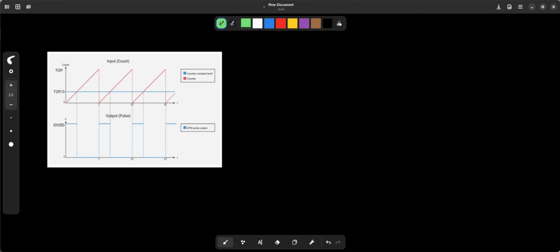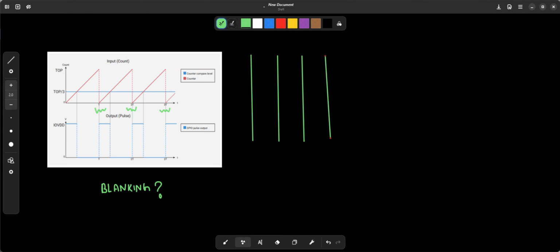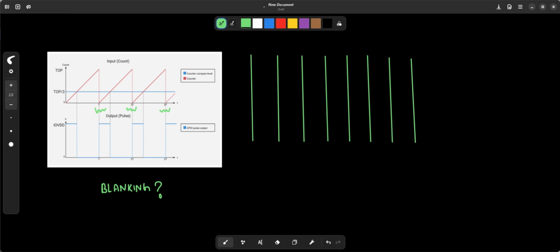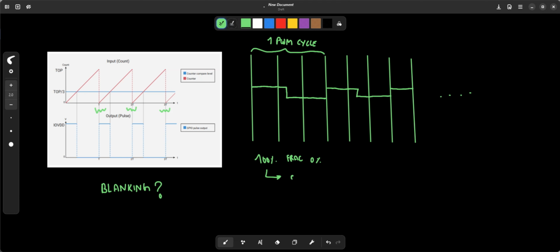Since complementary PWM makes a blanking interval at the end of each period nearly impossible to implement, I had to treat multiple PWM periods as one large unit. The last out of 10 periods is blanked, while the others are either fully on at 100% duty cycle or fully off at 0%, with one cycle having an edge. The number of full cycles is calculated as the input code divided by the counter wrap value of each individual cycle. The fractional cycle is just the input code modulo counter wrap, and the remaining cycles are 0.